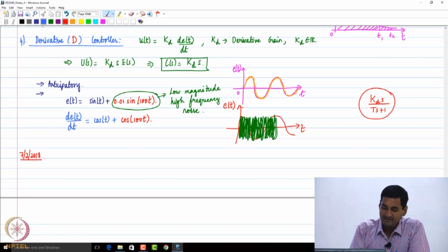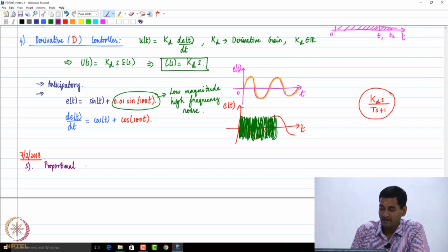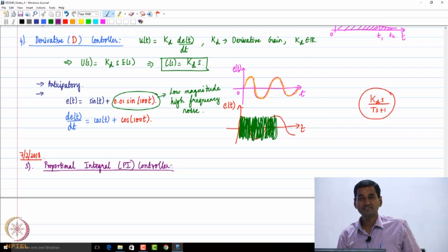By and large, one starts with proportional control. If things do not work out, then we try out proportional and an integral control, what is called a PI controller. If the proportional controller for some reason doesn't work, we can try the integral block alone.